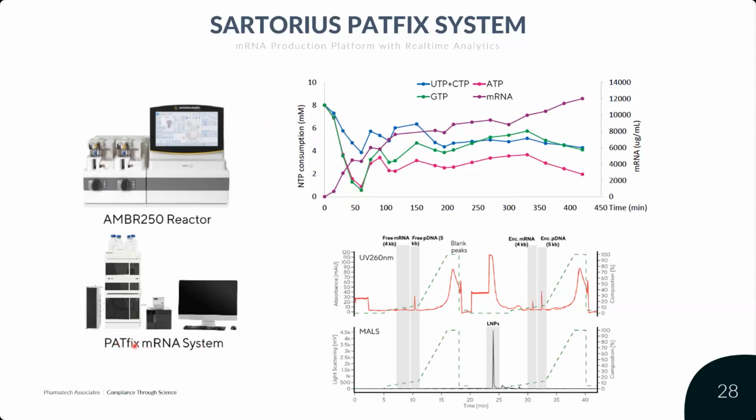And then one additional thing to think about is, as we talked about, combining PAT with chromatographic systems. If you could combine your chromatographic system with real-time analytics on the eluent coming out of your system, being able to analyze the amount of free mRNA, free pDNA, enclosed mRNA, enclosed pDNA, and the concentration of your lipid nanoparticles gives you much better real-time analytical control. So you don't have this lag between your process ending, sampling, and then sending your samples out for testing.